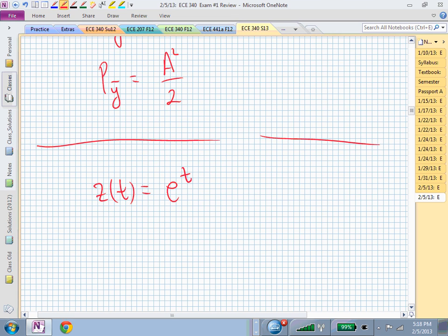Oh, okay. So I was getting hung up on just having a step, but you were switching on an exponential waveform. So now you're saying, let's say that we had a w of t equal to e to the minus t, and let's say u of t. Now that is an energy signal because you can find the area underneath that waveform, the energy integral. You could integrate all the way to infinity. It's going to vanish. So that endpoint or limit is okay. Question?